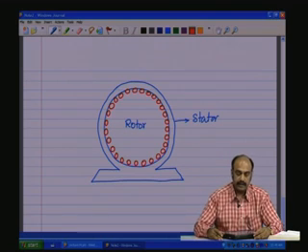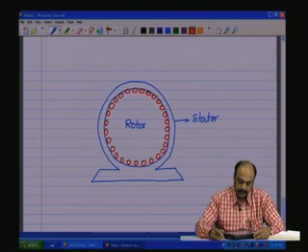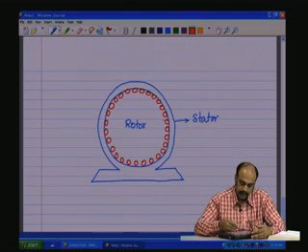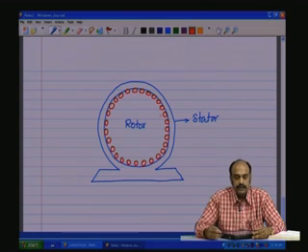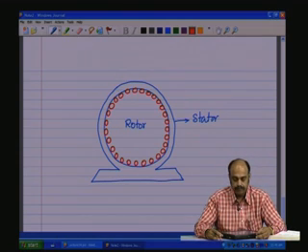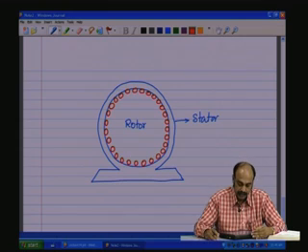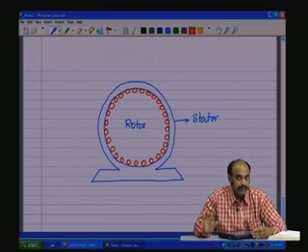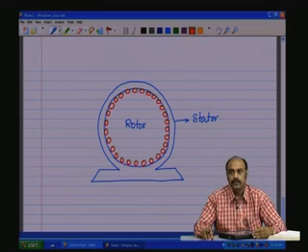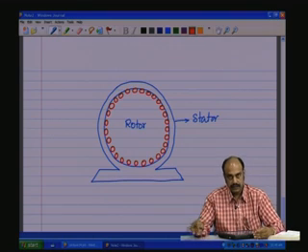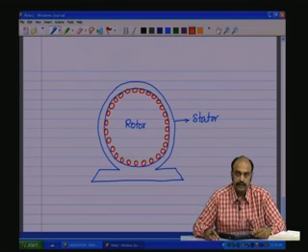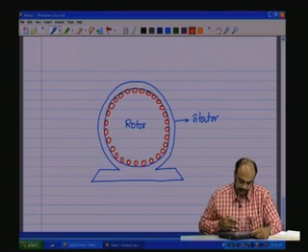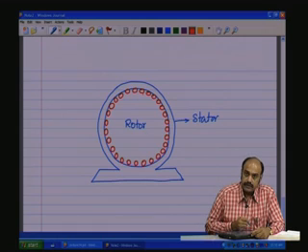That is why it is called the squirrel cage induction motor. In the wound rotor, the rotor coils are brought out through slip rings and brushes, like in the DC machine, but through slip rings, not a commutator, mind you. Which means the current in the external electric circuit is also AC.